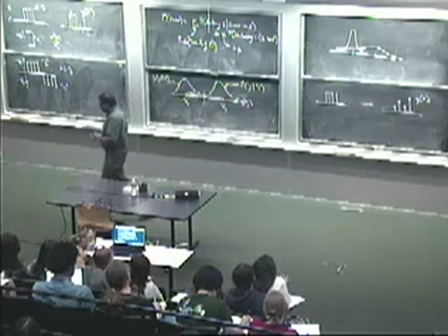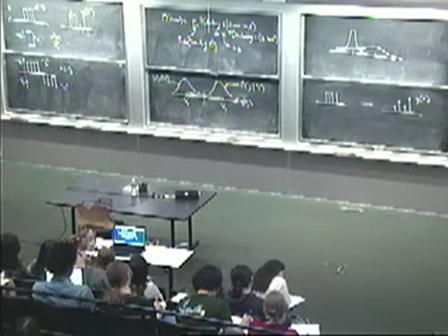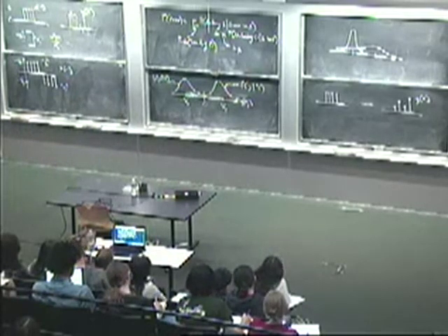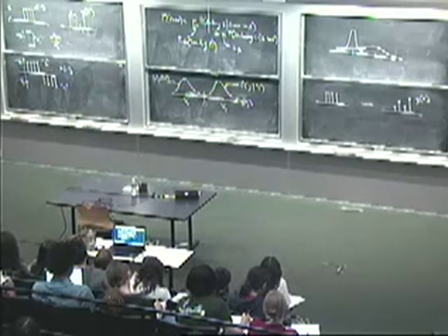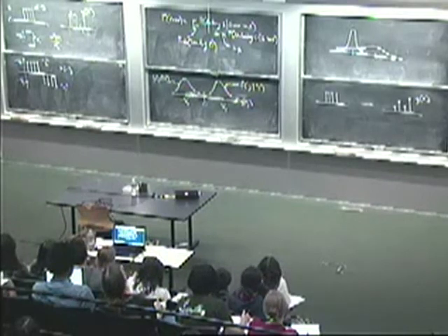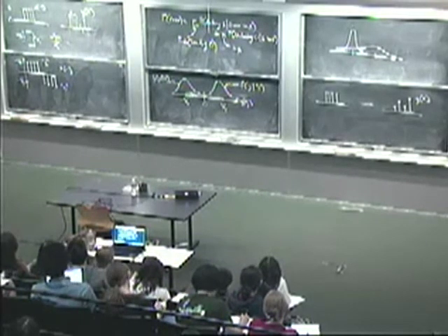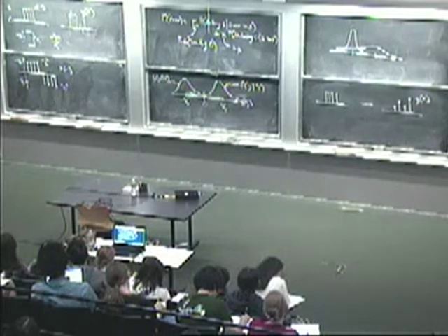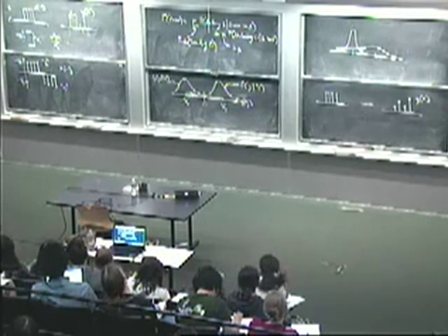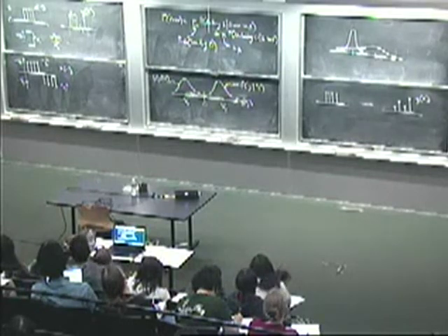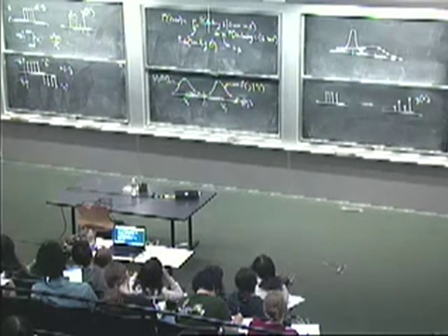Okay? So here's the thing. I've got a y of n, which is no longer just a constant plus noise. It's some known profile plus noise. That known profile is actually what the x of n is going to look like when it goes through the channel. I should perhaps have called it y0 of n, but let's stick to x0 of n.